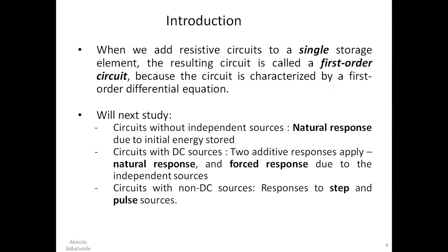We will be able to study circuits without independent sources, and those are going to be referred to as natural response due to initial energy stored in the circuit. We're going to look at circuits with DC sources. Two additive responses will apply here. The first one will be the natural response, and the second will be the forced response, which will be due to the independent sources. And then we will also look at circuits with non-DC sources, and this primarily focuses on responses to step and pulse sources. All of these we're going to discuss as we move on.